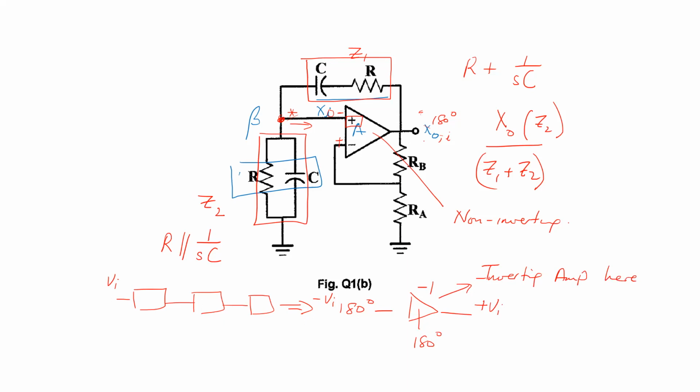So you have to watch the context of what you're talking about. For the Wien bridge oscillator, the network here is giving you 0 phase shift, so to satisfy the Barkhausen criteria, the amplifier has to take the signal and send it back out with a gain of approximately +1, right? In the case of some of the other phase shift oscillators, which are discussed in the oscillators 2 lecture, you could check it over.